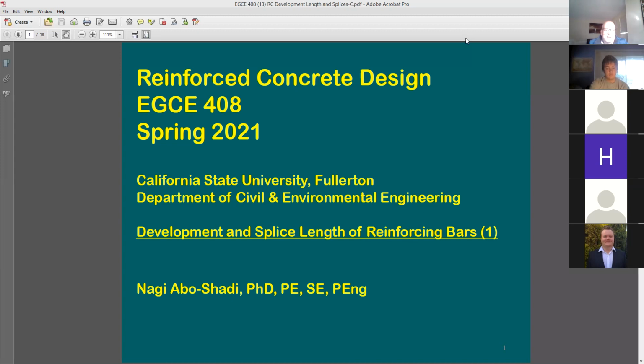you have the column load as dead load and live load. And then you have been asked here to do two major tasks. One of them is to size the footing, which means soil design, soil analysis. You're going to have your dead load and live load, you figure out the service load, and based on the allowable bearing pressure. Where do you get the allowable bearing pressure from? Just want to be sure that you know your way to do the problem.